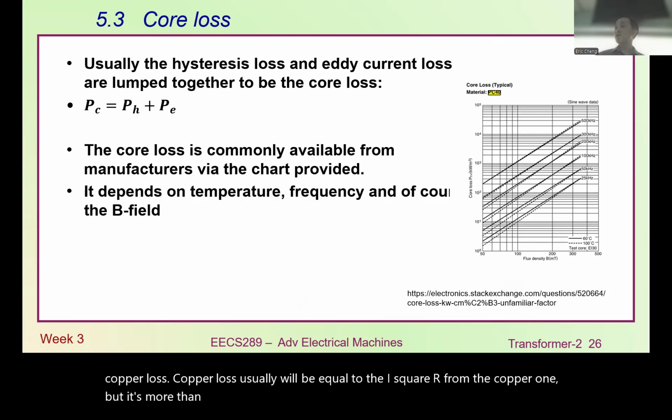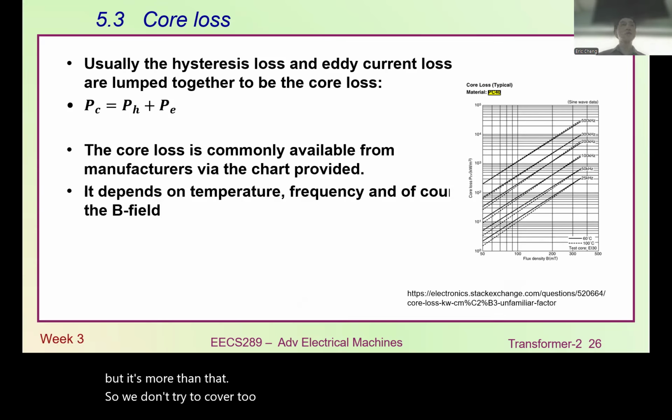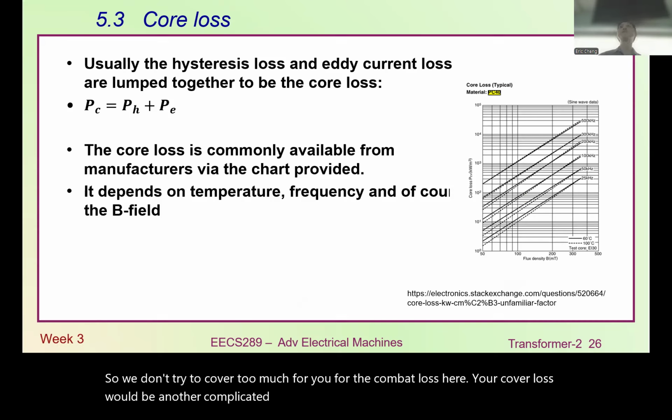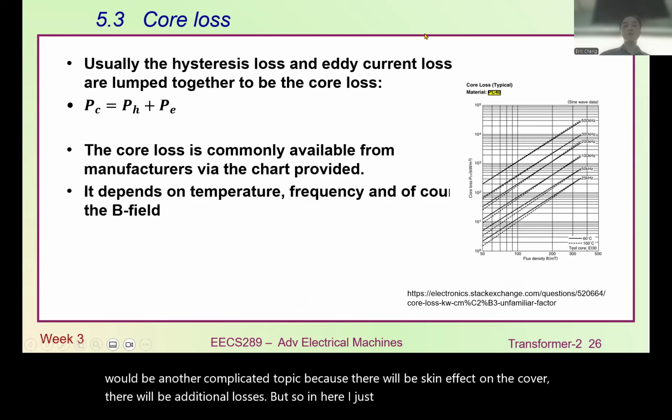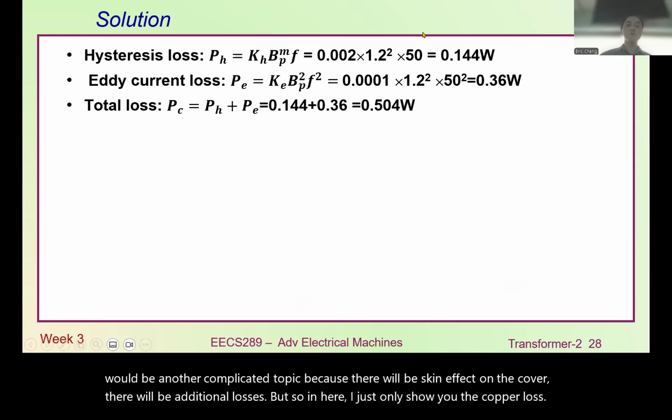So we don't try to cover too much for you for the copper loss here. The copper loss will be another complicated topic because there will be skin effect on the copper. There will be additional losses. So in here, I just only show you the core loss.